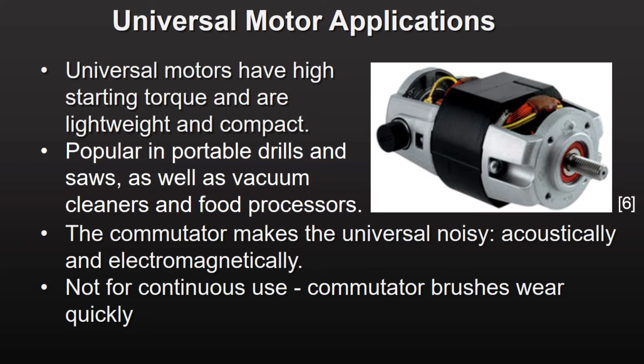Universal motors have some drawbacks that you need to be aware of. The commutator makes the universal motor noisy, one reason why the previously mentioned products make a lot of noise. They also emit a lot of EMI noise and they can throw off the performance of any nearby electronics design. Some companies use power drills as a quick and dirty way to test the EMI susceptibility of their prototype electronic products. In addition, universal motors are not for continuous use, as evidenced in the type of products they're found in. The commutator brushes wear quickly, and consumers are certainly not interested in getting their hands dirty changing carbon brushes.